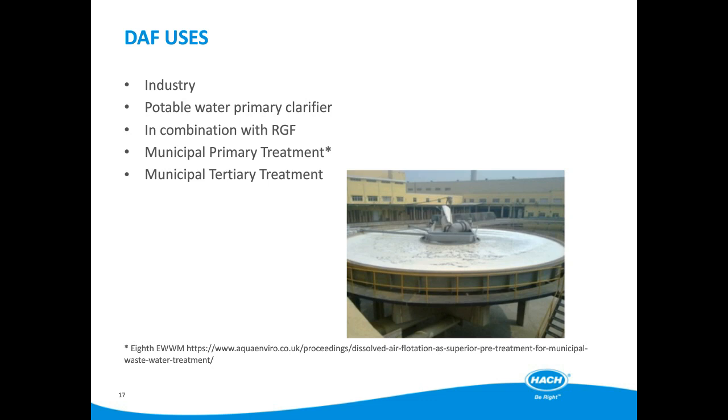For potable water, DAF plants are excellent for clarifying reservoir water, for the removal of suspended particles including algae, plankton and diatoms. The rapid solids removal rate of the DAF means the cell contents are not released to taint the water or increase chlorine demand.